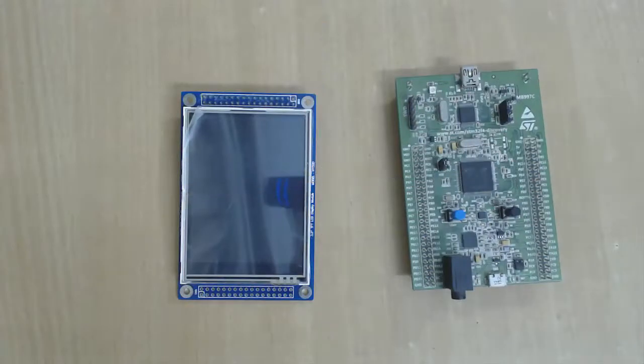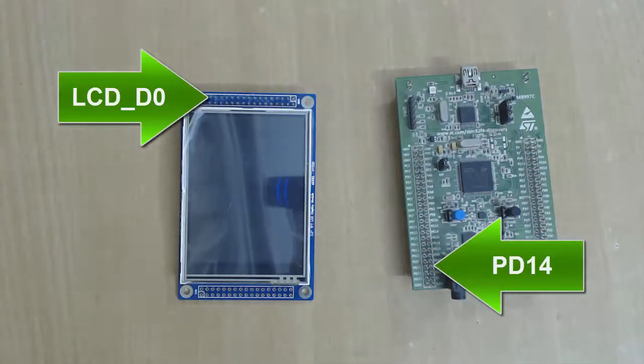Okay, so here we have the Discovery board and LCD. I will now start connecting the wires one by one. Let's first connect the PD14 pin from Discovery board to LCD D0 pin.